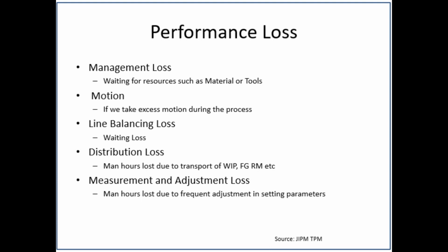The first one is management loss. Now what is a management loss? Waiting for resources such as material or tools. Motion loss, like in the last session I told you, if an operator is moving from one place to another just to take a tool or an inspection tool, he comes back again after moving 10 to 12 steps, then checks again, goes back and keeps them. So this is excessive motion which is causing my machine to be in a stopped condition, though it is available to perform.